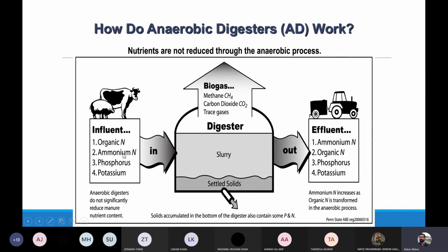So here it was not in a suitable form in terms of using this solid waste as a direct fertilizer, but after passing through this reactor, you have converted it into the biogas as well as slurry, and this slurry can be utilized as the fertilizer with the same content or the same characteristics which were added at the initial level as influent.